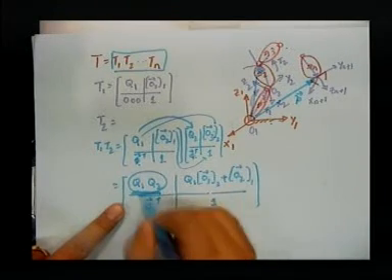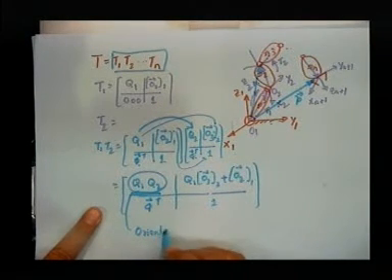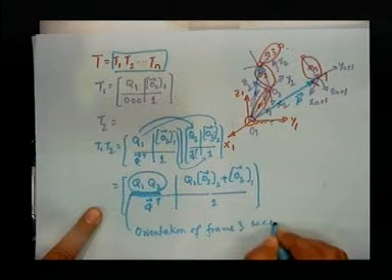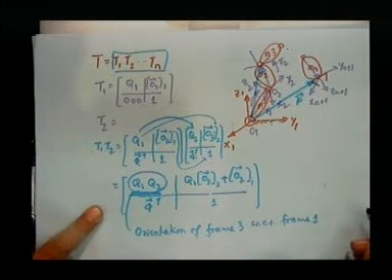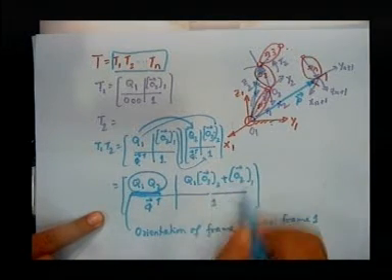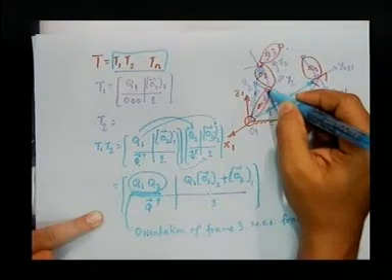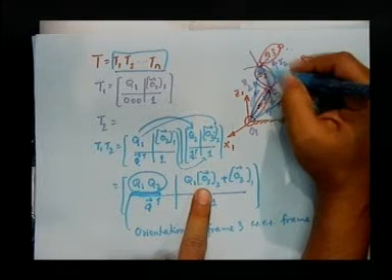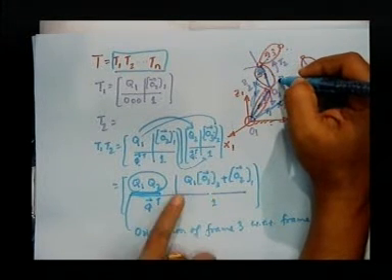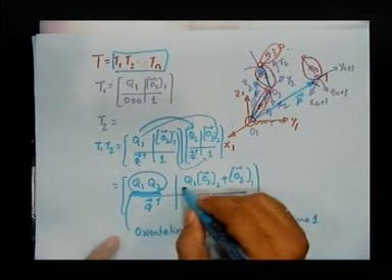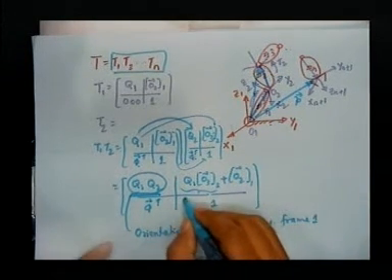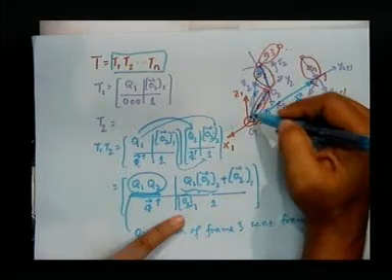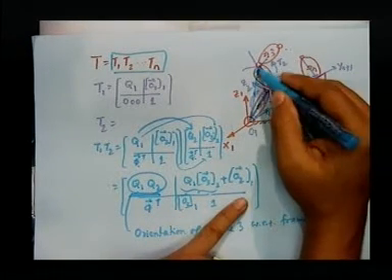So, this will be the orientation of frame 3 with respect to frame 1. That we will talk about. Now, if you look at this one, this is my O2 in frame 1, from here to here. Then this portion is O3 in 2, that means O3 is represented in frame 2, but I am multiplying with Q1, which means this portion is O3 in 1. So, O3 in 1 and O2 in 1. This vector I have represented here, and this vector here, I can then add them up. So, this gives me this one.